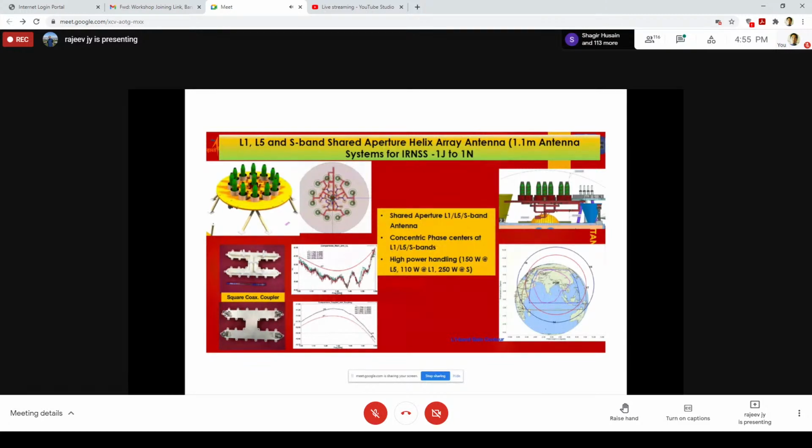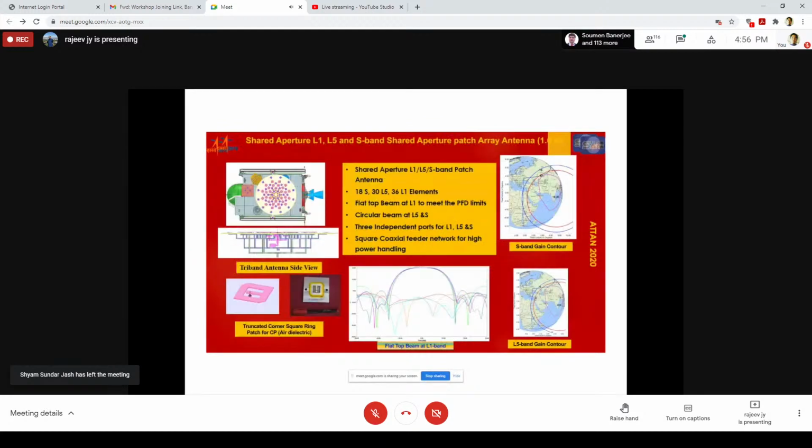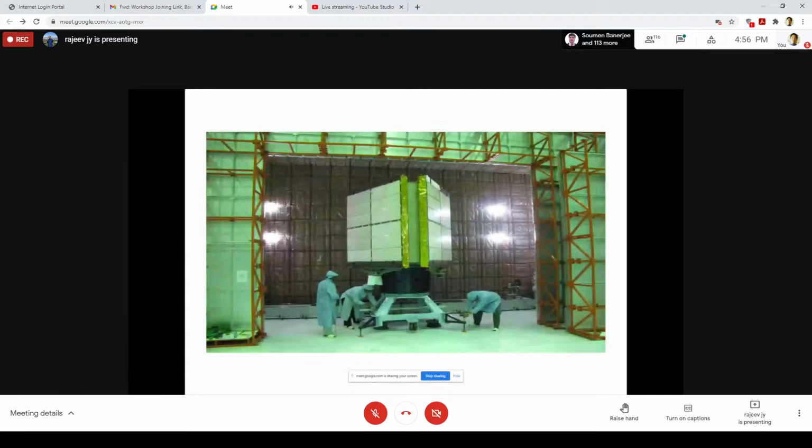That is being shown here, and we use method of moments or FEM, finite element method, and we have our own codes, some of them tailor-made for the requirements. They are used for finding out the currents, the input impedance mismatch, or even for ray tracing. If we consider a high frequency, then we can even use geometrical optics. Now, this is what I covered about the helical antennas.